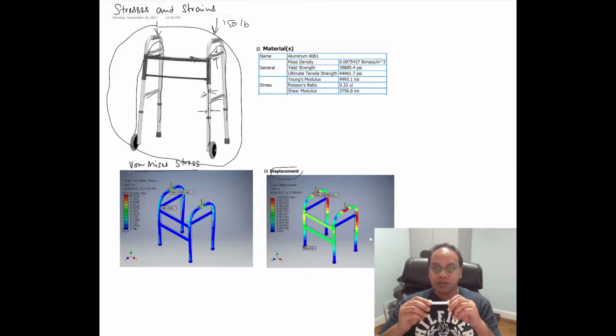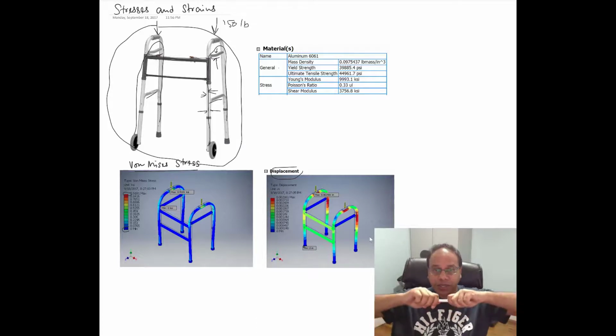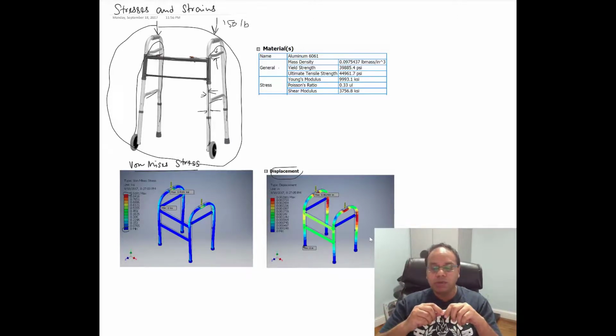I have this material, this is chalk, your regular chalk, and you could actually apply different kinds of loading on it. So I'm going to demonstrate this to you by applying 3 different kinds of loading. So one is that I could apply tension on it. So I could pull at both ends. Okay, so let's see what happens when I pull at both ends, and it fractures. So you know that when you pull it from 2 sides, it is not going to deform at all. There will be no appreciable deformation, at least not what you can see. Okay, so in this case, it instantaneously broke.